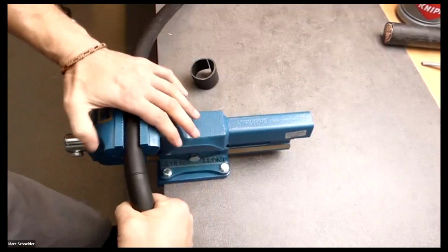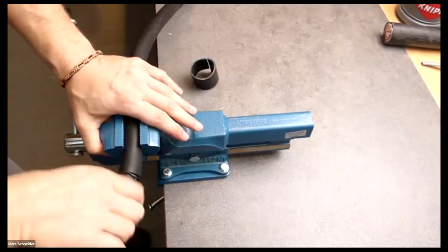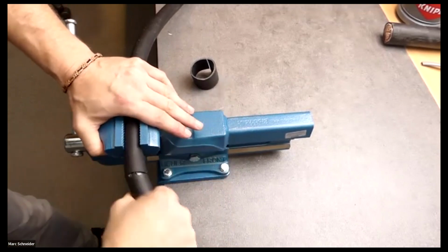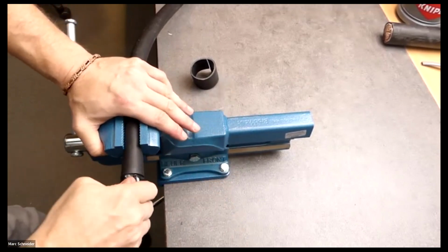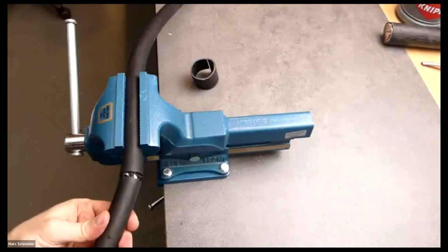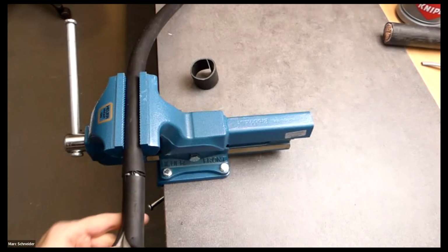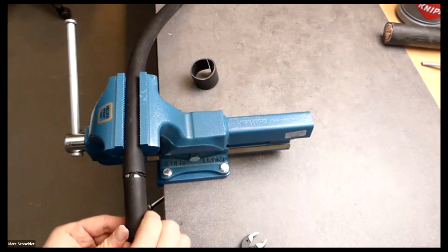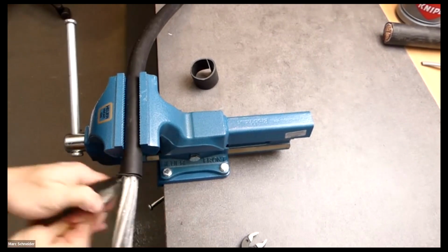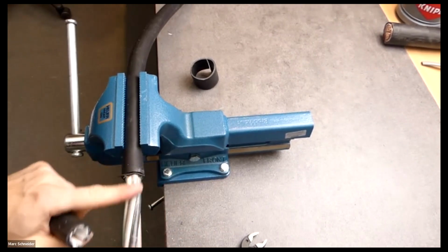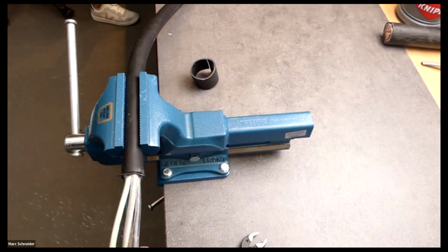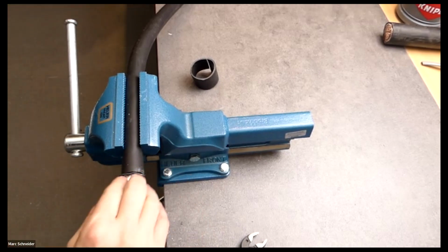So, not cutting, scratching, and bending. So we have to bend it, and now you can use water pliers or other tools to remove the outer insulation. And you see here, nothing of the underlying cables is scratched or damaged. This is very important, so as not to damage the other insulations.